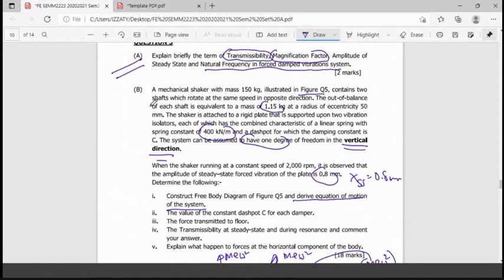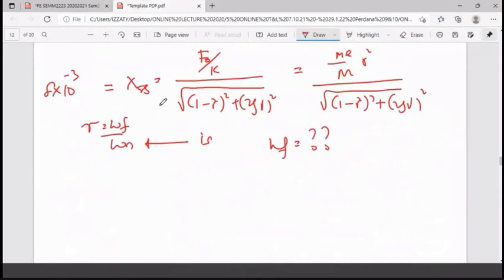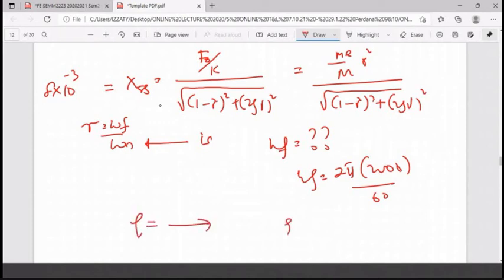The next thing is to define omega F, which is basically the speed given here as 2000. So omega F will be 2000 times 2 pi divided by 60. Yes, correct. So you have the R, correct? You have the zeta calculated earlier. Then you know what will be the M e over M. Then you have the M, so you have the zeta. Please be ensured that zeta must lie between this one. This is the range of the zeta.